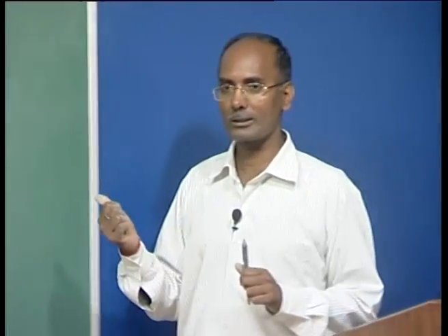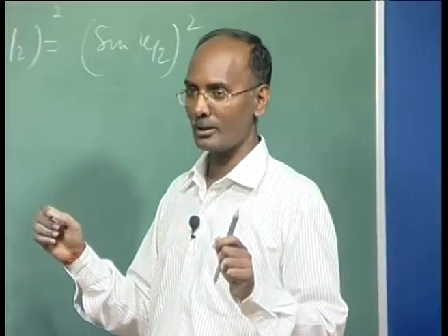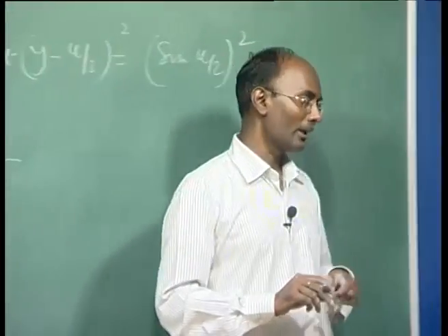In the second lecture I started with the three phase rectifier circuits, and we used the grouping, how the commutation group Q value was decided. We also introduced R and S, that is the series and the parallel. We derived the voltage equation for those simple three phase rectifier circuits. Then in lecture number 3, I started to go for what should be the better configuration of a converter circuit. In that we saw the various features.